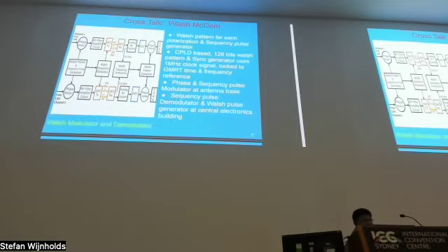At this stage, the sequency pulse, which was modulated using the 105 MHz signal, gets demodulated. Then the RF signal goes to the analog receiver system and then gets digitally converted. The digitally converted signal gets phase demodulation using the Walsh pattern, which is similar to the one used at the antenna base. After demodulation, the signal goes to the remaining part of the correlator.